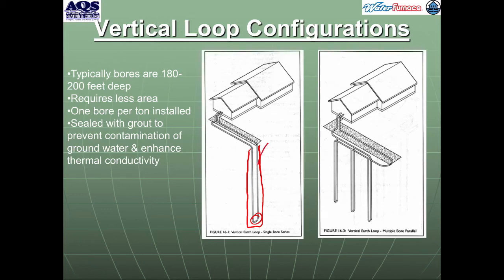And then they fill this with a grout. So the whole pipe is actually buried in a thermally conductive grout, and that allows for good conductivity to the ground, which is very necessary. What you don't want is air to act as your conductor, because that just doesn't work as well. So that's typical of what it would end up being on there.